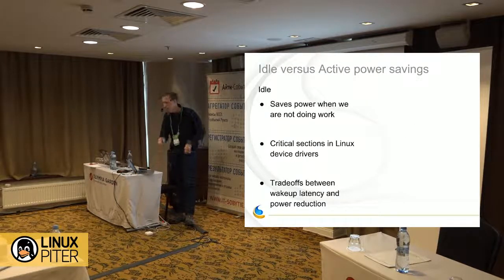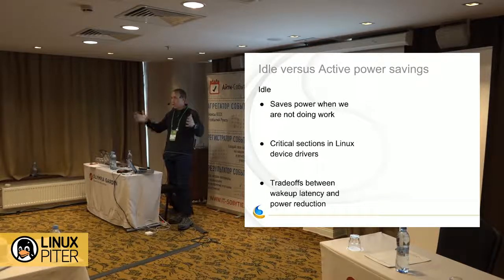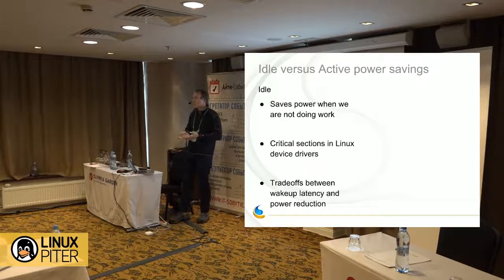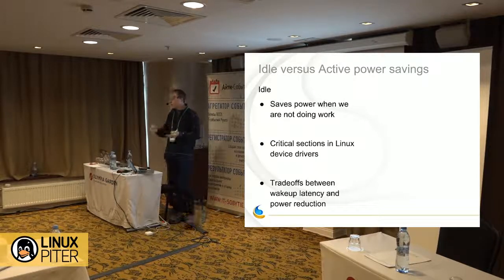Every type of power-saving technique can really be put in one of two buckets. You have active power-saving techniques, which are ways to save power while you're doing work, while you're running. And then you have power-saving techniques while you're not doing work, while you're idle. This is basically the dichotomy for the whole power management universe. The most basic and obvious way of saving power is to turn something off. You're idle, you're not using it, just turn it off.